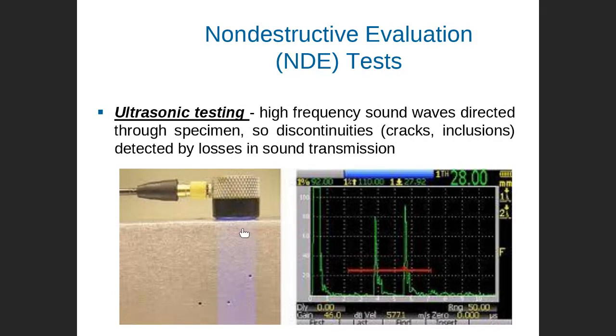So this one mainly relates to the speed of the signal. You send a signal, it goes and comes back. The speed will be different if the signal faces some cavity or some defect below the surface. In this case, you get a peak, and you get another peak. Then they realize this is one peak related to this one, and this is another peak related to the other one.